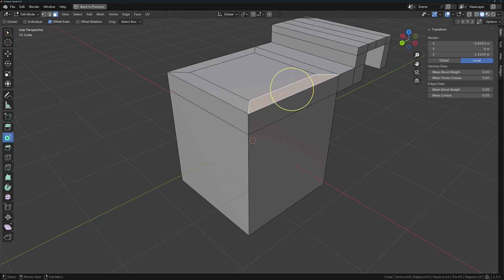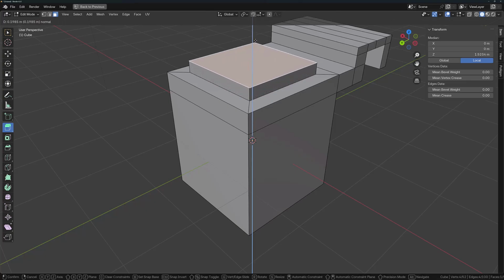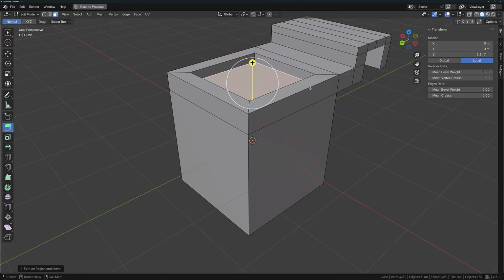So everything is still on the same plane if you like, but we're now actually extruding and then scaling directly inwards, which is slightly different to the extrude tool, where we can click and drag, and this will change the actual shape of the model straight away. By the way, we can use extrusions to extrude out or into our geometry, just as I've done right here.